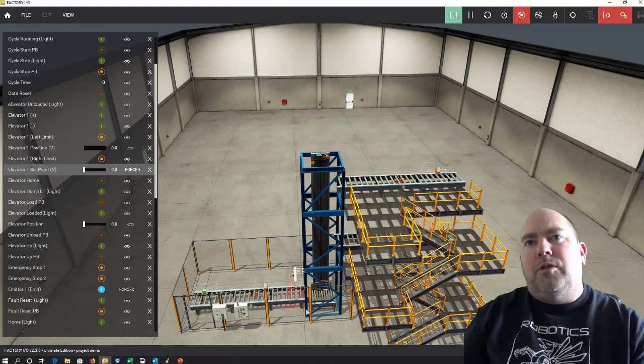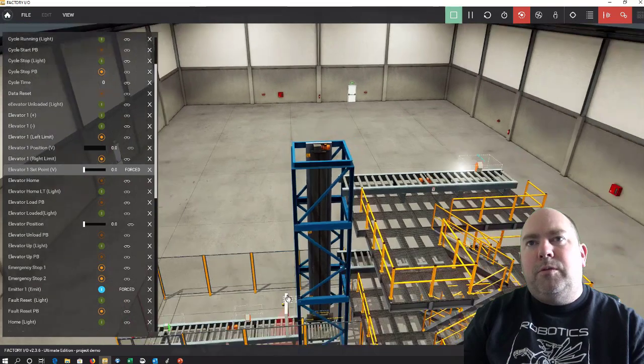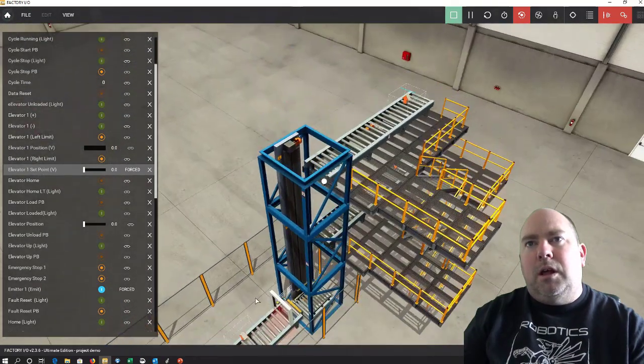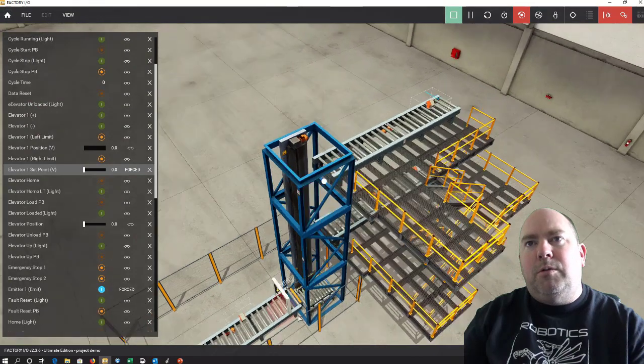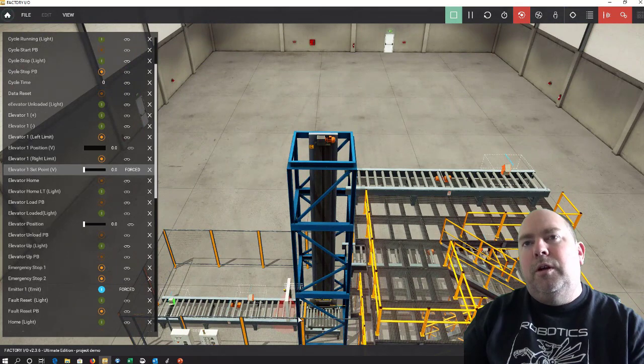So we will use a sequencer. So basically we'll run all the conveyors all the time. We'll determine with this vision system what type of part we have. And then we will run a sequence. We get a part at the roller here. Roller will drop, part loads in.